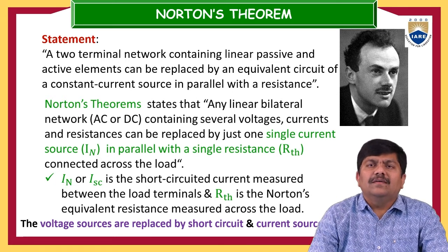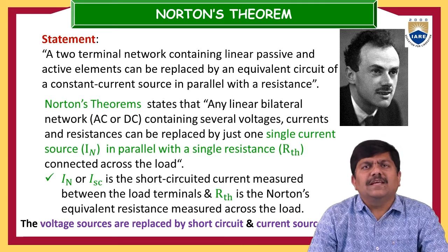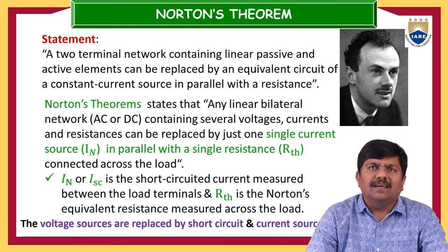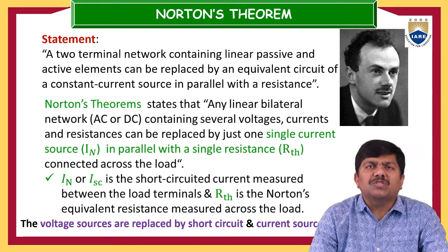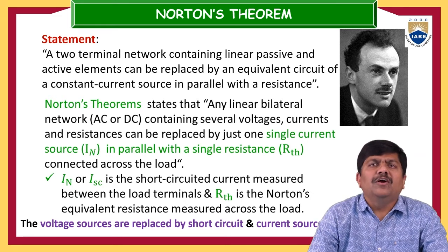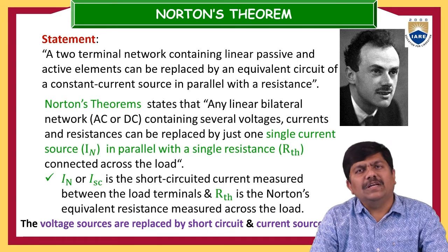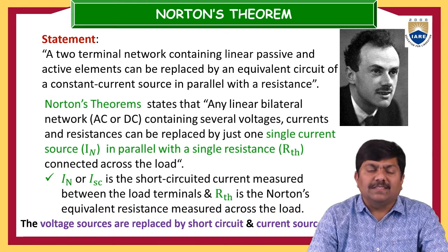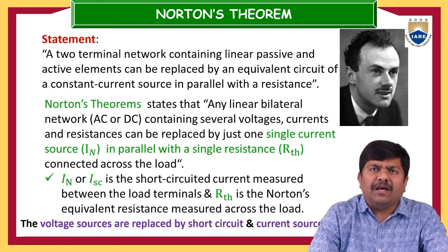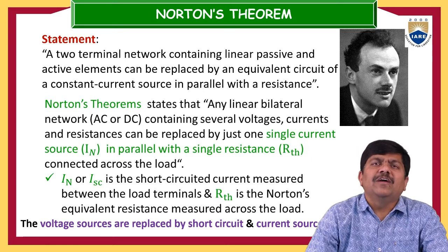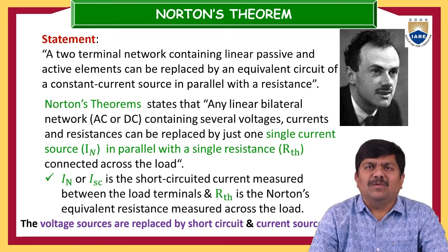Here, the voltage source is called Thevenin's equivalent voltage, and the resistance is Thevenin's equivalent resistance. This is what we started with, and we make use of Thevenin's principle to find the currents or voltages across, or through, a particular resistance. I am narrating all this about Thevenin's Theorem because the flavor of Thevenin's Theorem we are going to utilize in Norton's Theorem also.